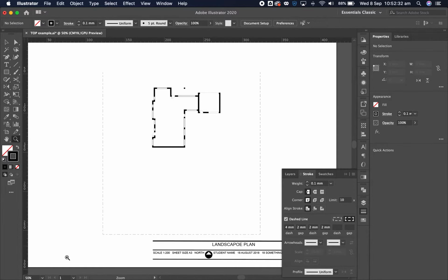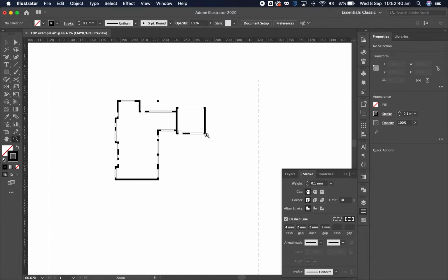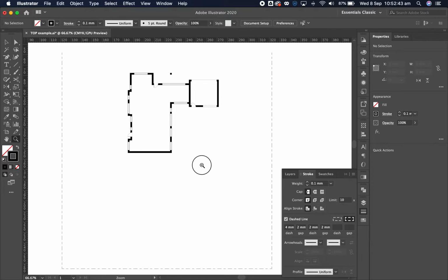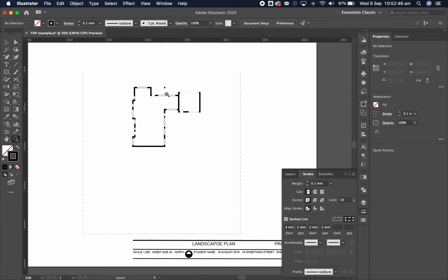Okay, you can add a key to this explaining what each line is. And you'll need a key for this as well, and I'll explain to you later on why we have that key. All right, so topographics. You understand it now that we have a thick line as being a key, and a thinner line is an increment within the contour line. So depending on the slope of your block, it depends what type of key you use, the values for your key and the smaller increments.